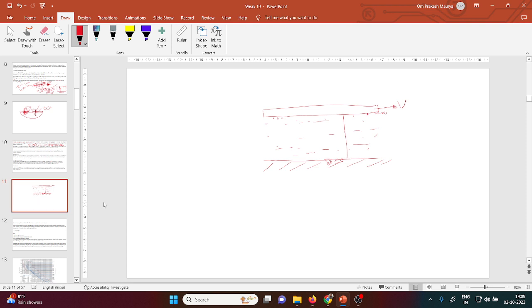So Francis, if both the plates are moving, then we will be having non-zero velocity at the top and bottom. I mean, if the plate on top and bottom is moving, then the fluid at the top and bottom will be having a non-zero velocity, the velocity of that moving plate. Yes, definitely. The no slip condition means that only. No slip condition is not like that the velocity is always zero. But no slip condition means if the plate has velocity v, your fluid also has velocity v.